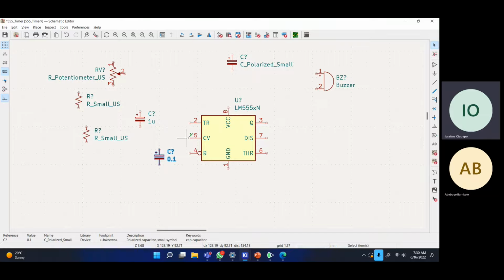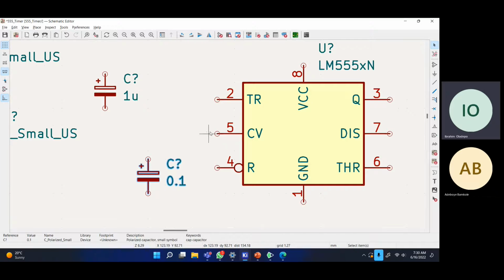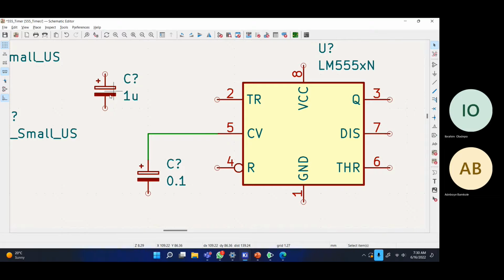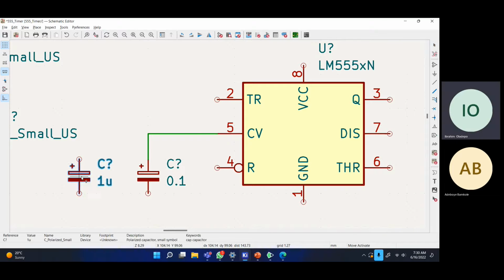Once I place my cursor on top of this circle here, can you see? Once the cursor comes to the top of the circle, you see this green symbol. That symbol is for wiring. It tells you that you can wire that point. If I come here now, you can see I can wire this to something else. And if you don't want that, you can always come here to the Add a Wire option here on the right side.